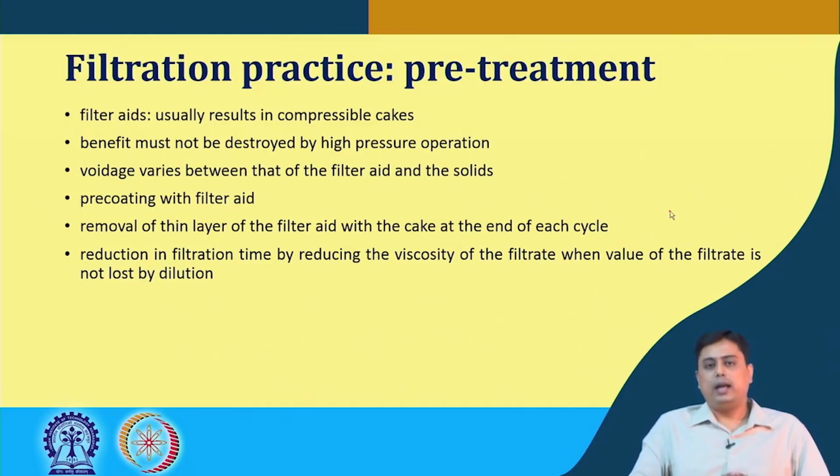And also at the beginning we mentioned that the reduction in filtration time can be achieved by reducing the viscosity of the filtrate when the value of the filtrate is not lost by dilution. In such case, we can try to dilute the suspension to reduce its viscosity and have the filtration. But in that case, we have to keep in mind that the value of the filtrate is not lost.